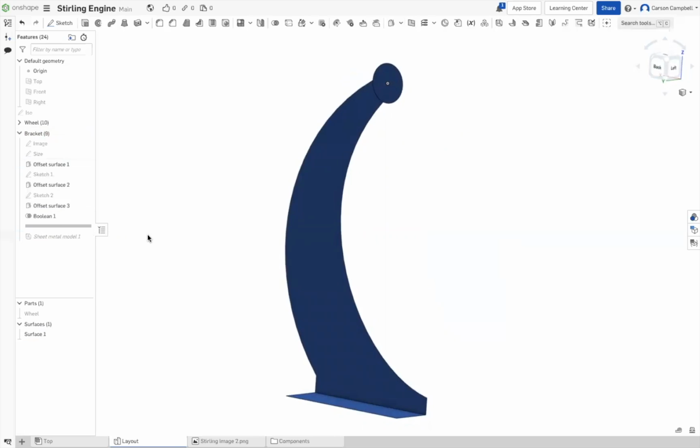Okay, and I'm going over this. It's nitpicking, but this is just a sheet metal part, and you're constantly going to be fighting. How many surface patches do I have? How many sheets do I have? And then they come along and they knit 2 surfaces together. The patches are still there, they're defined, but the system, when you knit them together, just groups them. It truly isn't one surface. To go in and work with just the circle, to your original question, with the original edge, we'll be fighting the system because it thinks it's all one surface.